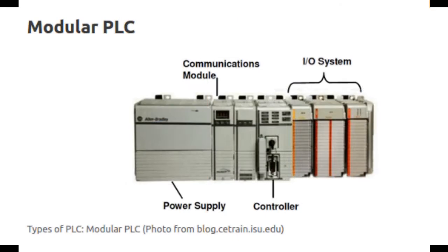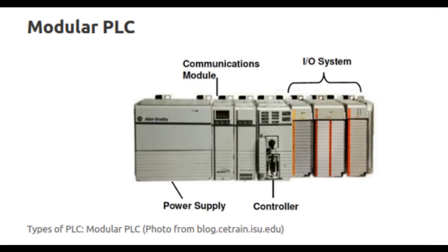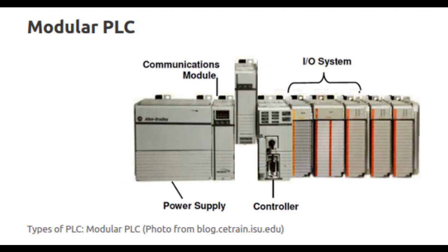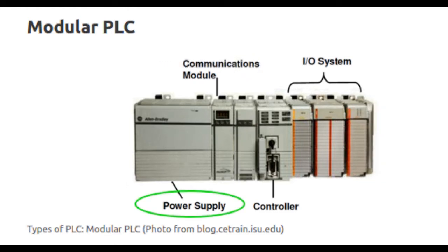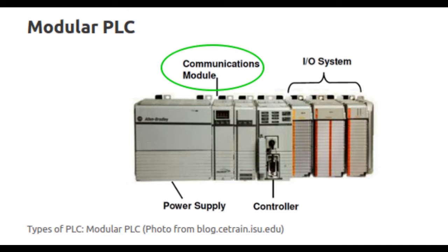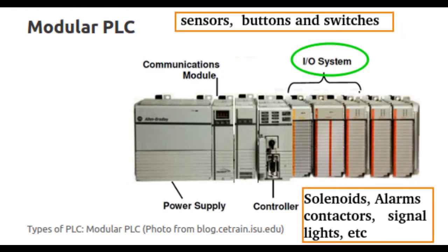They are cheaper and suitable for small projects. However, in the field, you are more likely to encounter the modular PLC. The designing engineers will add modules as necessary, and faulty modules can be replaced in the field. Here, the power supplies are to the left. The communications module will be connected to the network, probably via Ethernet, and things like encoders, temperature sensors, proximity sensors, push buttons, and switches are connected to the input modules, and solenoids, alarms, contactors, signaling lights, those are connected to